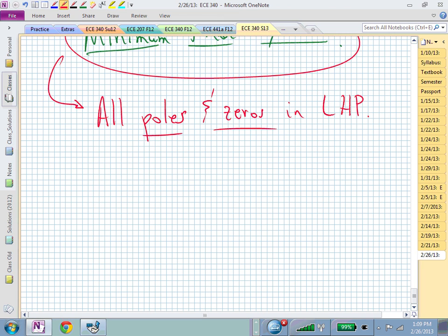No, a non-minimum phase system typically means that if you wanted to go to the left, you start to go to the right first. Meaning if I commanded a system, let's say that I had some non-minimum phase system with a right half plane zero, and I said, I'm really wanting to approach that line, that's my command.